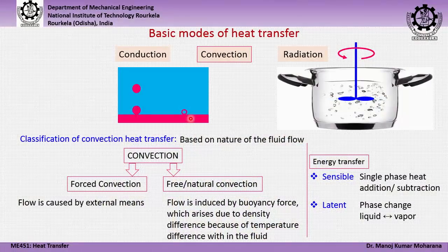So, near the surface a small bubble will be formed, and with gradual addition of heat the size of this bubble will increase, and once the bubble achieves a certain size, it will start moving vertically upward. This will happen because of the buoyancy force acting on the bubble, and when this bubble moves upward, it will also create a disturbance to the surrounding fluid, then there will be movement of the water in this container. So, this change in phase from liquid to vapor is called your boiling process,